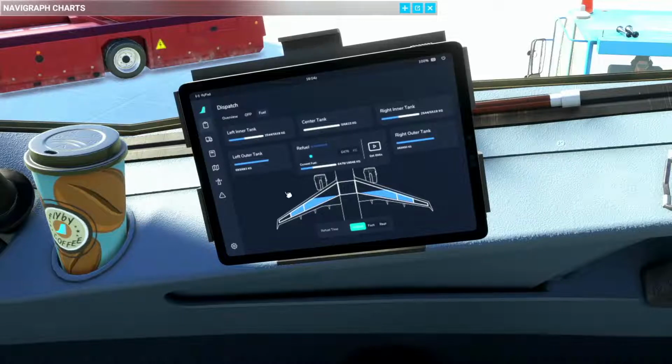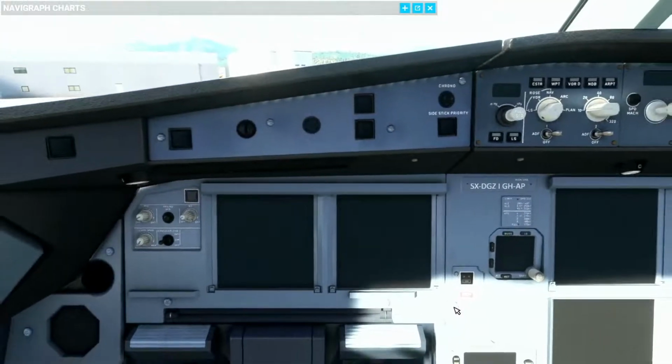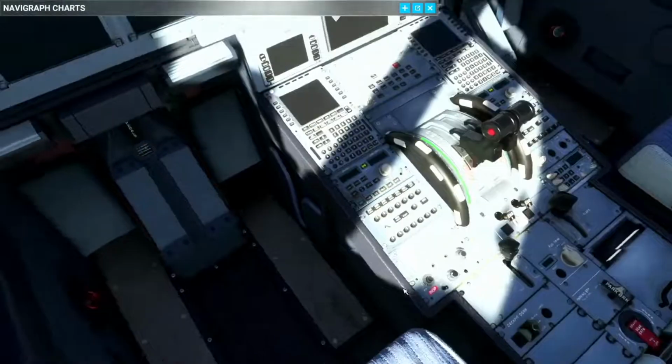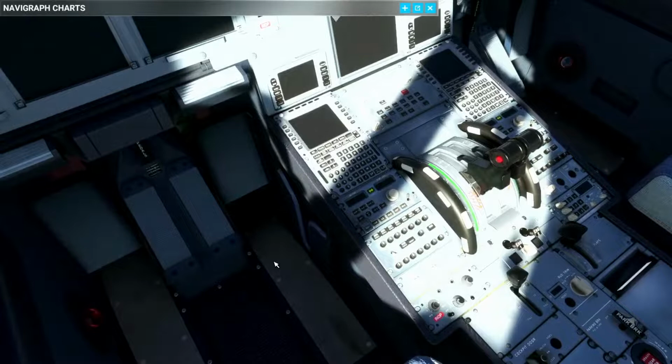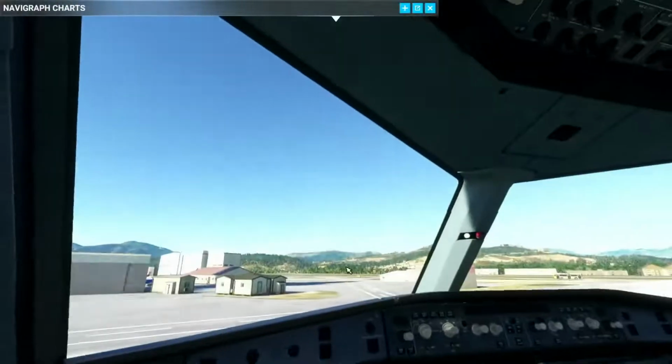Next, let's start with the cockpit preparation. First of all, we'll check all the levers, whether they're in the right positions. The parking brake is set. We'll check that the flaps are up. The spoilers are also here, so just in case they were somewhere else, we can turn them to the front. Thrust levers, quick check if they are nice and idle. And the other one is the wipers on top here that we have to check.